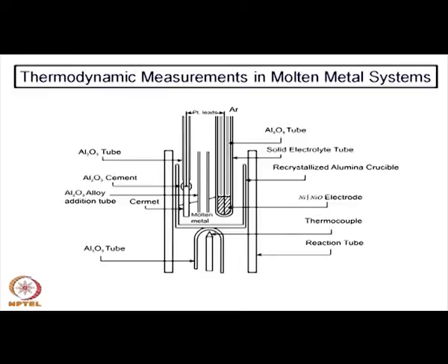Just like in an automotive engine, you have a combustion process going on in industrial furnaces, even ceramic furnaces, ceramic kilns. Many of the ceramic kilns today are fitted with oxygen sensors, zirconia sensors. Again, the purpose is primarily to control the combustion, so that you get the complete utility of your fuel. There is no excess oxygen or excess air in the system.